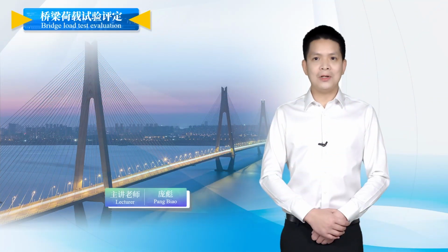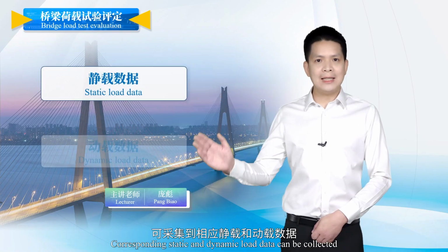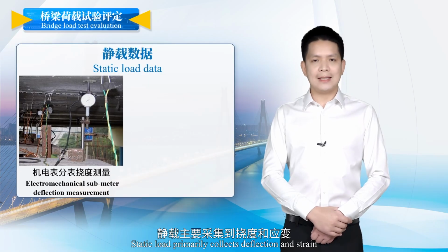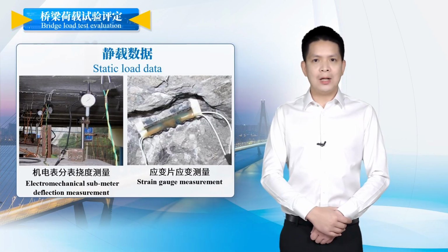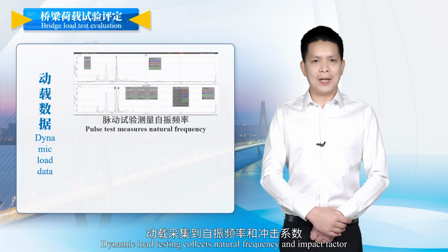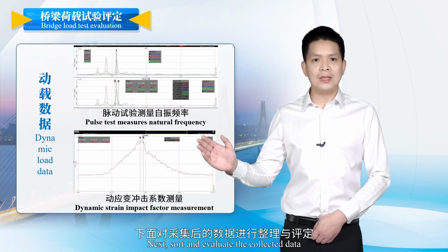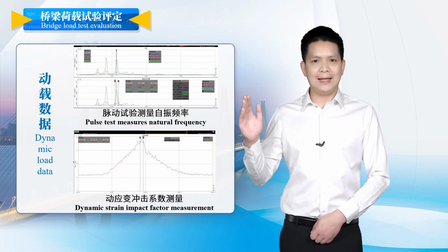During the load test, corresponding static and dynamic load data can be collected. Static load primarily collects deflection and strain. Dynamic load testing collects natural frequency and impact factor. Next, sort and evaluate the collected data.